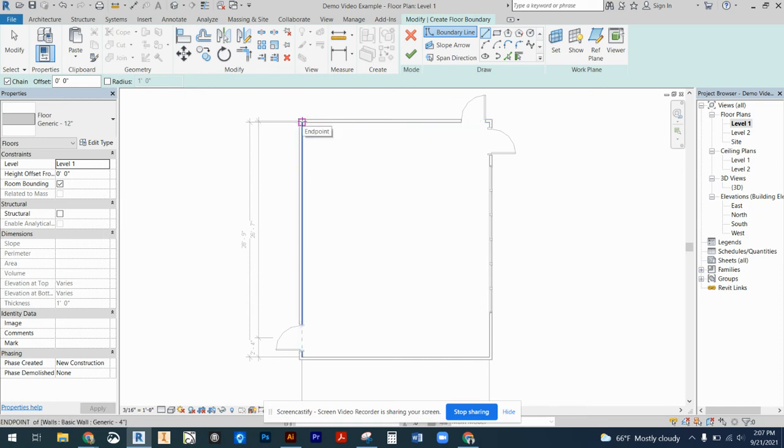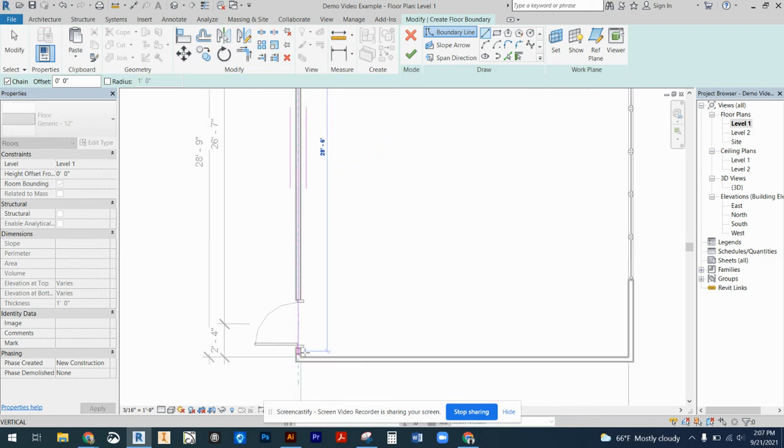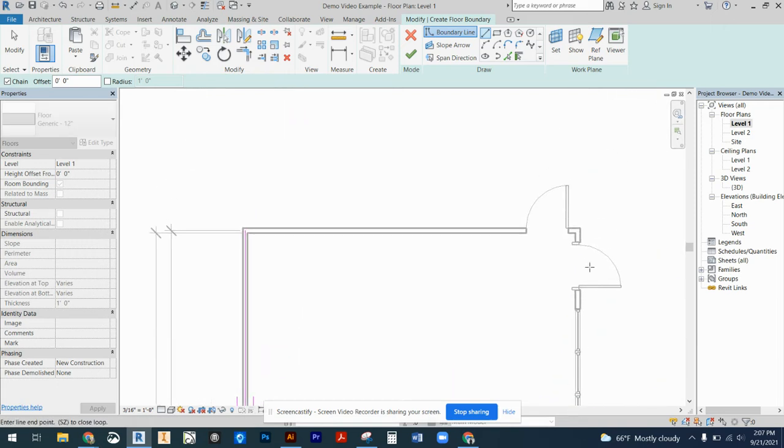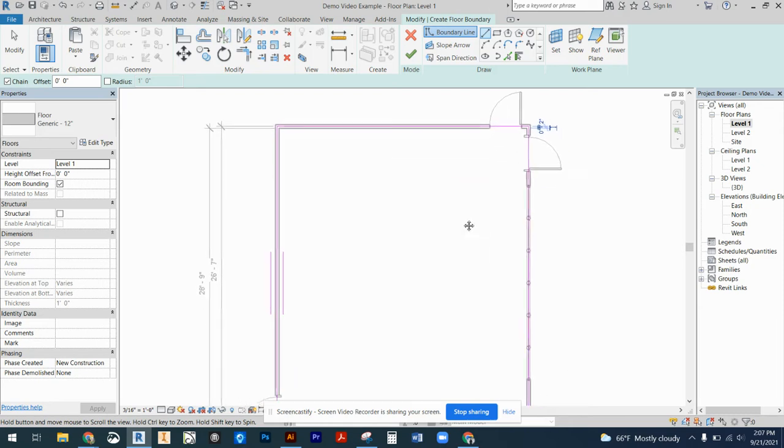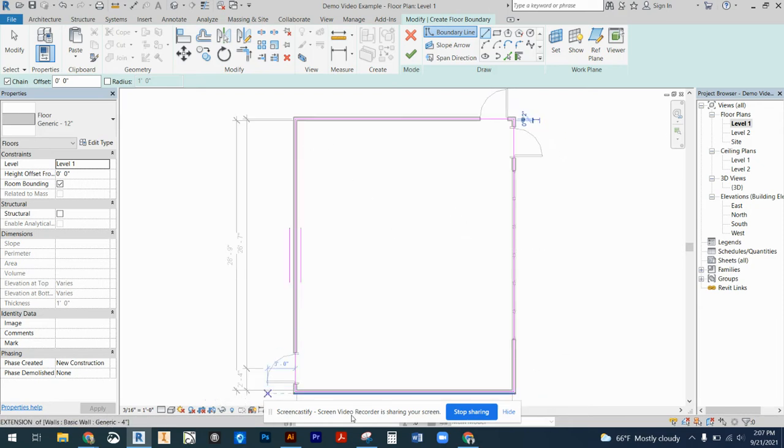And my rule of thumb is to create the flooring from the inside of the room. I know sometimes we're tempted to do the edges, and you can do like the center lines if you want to use the tracking lines that'll go ahead and show up. And you can do center of wall to center of wall, especially when we get to our house floor plans. That might be a nice practice, but you're literally just going to go around the perimeter and create a closed object around the perimeter of our classroom. Again, I'm not using our classroom shape, but you would go around the perimeter of all of the walls for the classroom assignment. I'm keeping this one nice and square.